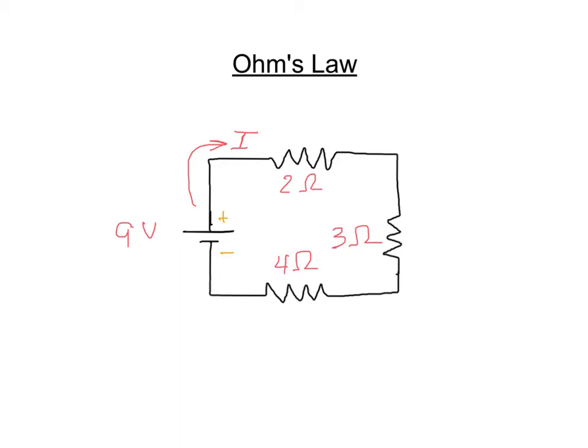Because these are in series, the same current flows through all 3 resistors, that value I there. We don't know what it is, but we're about to figure it out. Ohm's law says that voltage is equal to current times resistance.